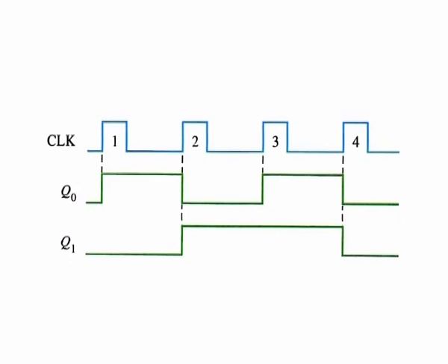Notice that all the waveform transitions appear coincidental, that is, the propagation delays are not indicated, although the delays are an important factor in the synchronous counter operation. In an overall timing diagram, they are normally omitted for simplicity.